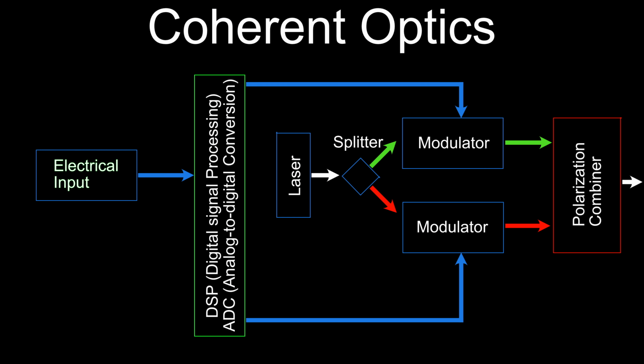Again, this is a very simplified description. Technically, there are 3 bits per step, and the process is much more complex, but I think this description will get the basic point across. We're undergoing a similar shift in the optical world with something called coherent optics. Right now, optics are using PAM encoding and function much in the same way as Gig-E does, only with an optical medium. However, coherent optics use a laser that produces a fixed beam at a specific wavelength.